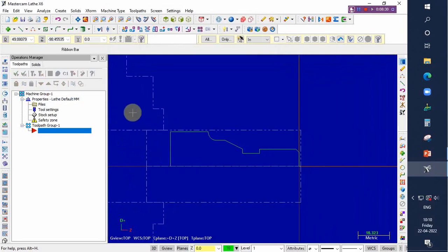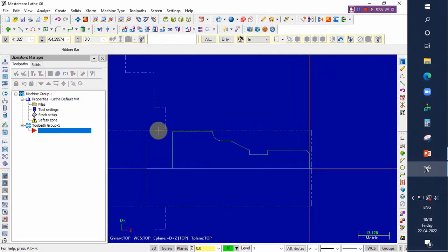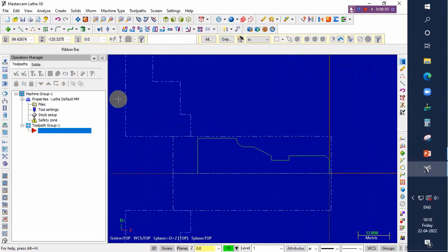Now we have the chuck, we have the component. Say inside 10 mm is there, outside the rest 5 mm. This is nothing but a clearance between the chuck and our component. After completing 75 mm length, the tool has to retract freely without touching the chuck, so we are leaving some stock gap. And then the next step, simply we are going to select the tool paths.